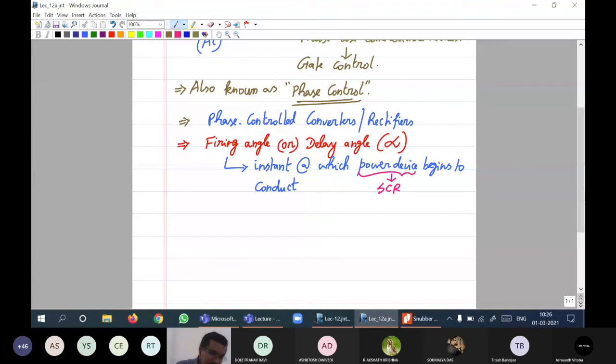Next class, I will take up a simple circuit, which will be a half wave controlled rectifier. And then we will try to understand that circuit principle later on. I told natural commutation. Anyway, we will discuss all these points tomorrow with the help of some waveforms also. It will be easier for us. Natural commutation. Commutation means the process of turning off.